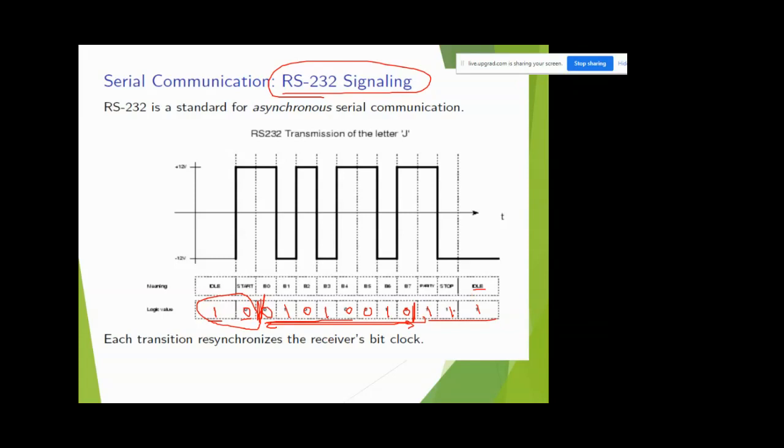This type of synchronization, or the addition of redundant bits, is called bit stuffing. The bit stuffing that we are using is to correct bit errors and to maintain synchronization between the frames. Along with the information bits we are adding some extra bits at the start of the sequence of information and at the end of it. Now this is the overall bit pattern and this is the representation. For bit 0 you can see the positive level, and for bit 1 the negative level.